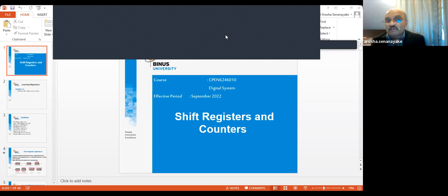First we will look at what the operations are, as I told you just before, serial to parallel, for example, the key entered. Then the types of shift registers, where data as input comes in and produces outputs differently depending on the type of shift register. At the same time, you can have bidirectional shift registers, one moving from left to right, the other right to left, or rotation, most probably.